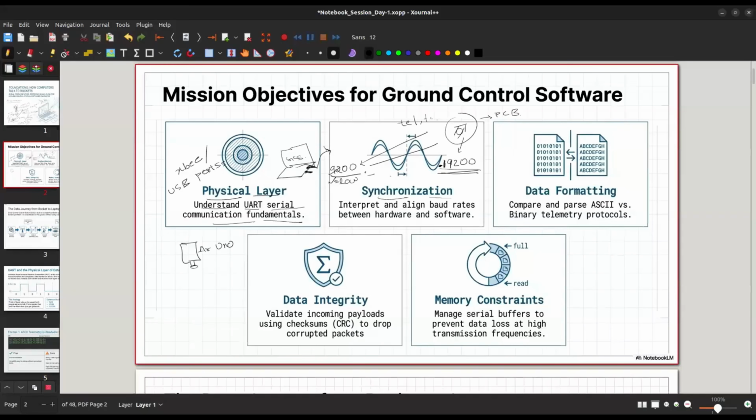When you buy this Arduino Uno, you get a USB port. This is your USB cable, and this is the Type C of the USB cable. So basically, USB is this cable. When you're building a ground control station and trying to test that the functionalities are all right, you're not going to test your real rocket for that. You're probably going to insert an Arduino Uno and program it in a way that it will simulate the data. That is a standard GCS building practice.